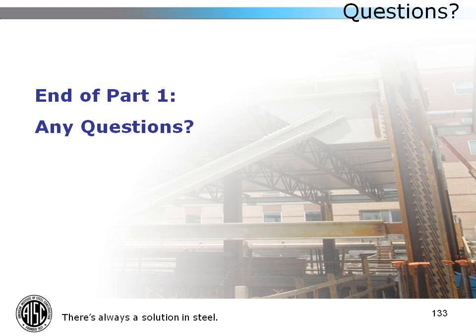Okay. All right. The next question is, where steel W sections are embedded in a shear wall and used to carry most of the tension in a shear wall at the base, can the load transfer from concrete to steel or steel to concrete be done using angles welded to the steel flanges?